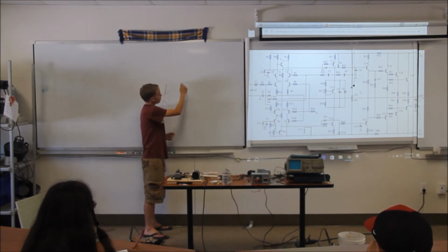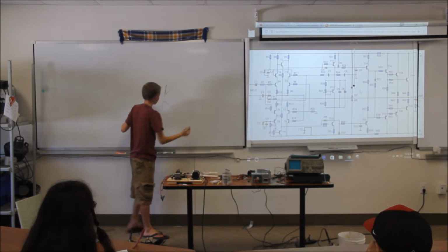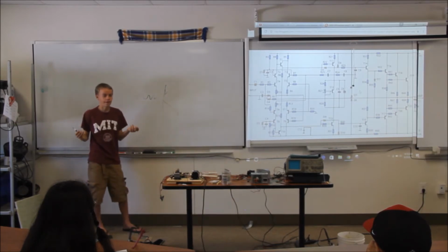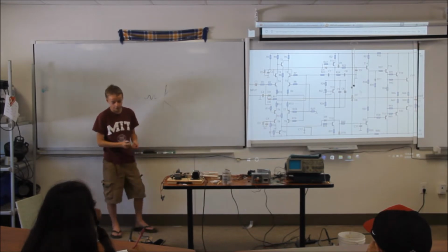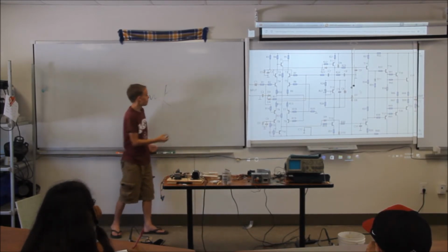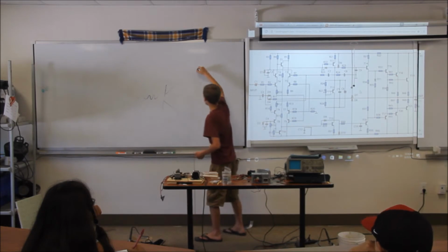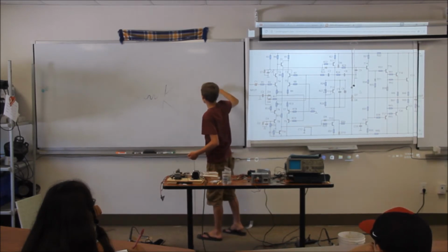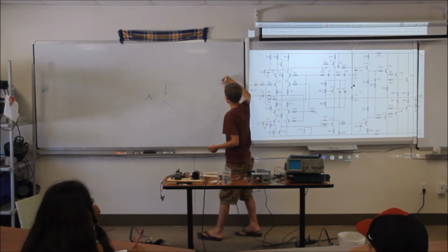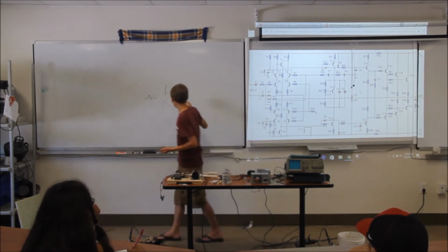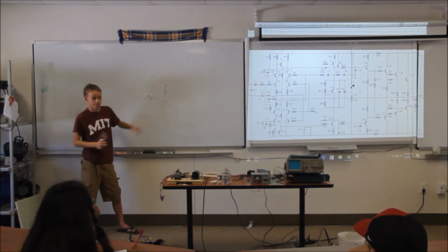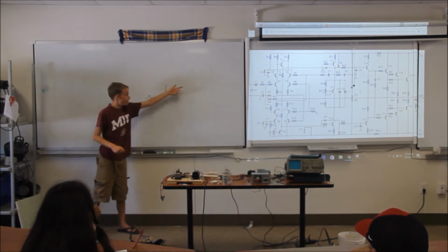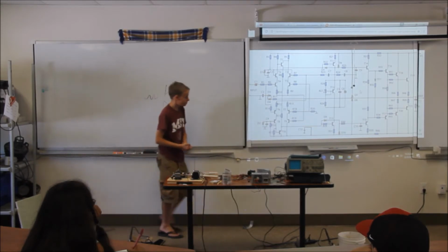That voltage would be however much gain the transistor has. So if this one was 0.5 and the transistor had a gain of 10, then this sine wave coming out of the transistor would have a voltage of 5. Because if the gain of this transistor is 10, then the output voltage will be 10 times the input voltage, which is 5 volts.